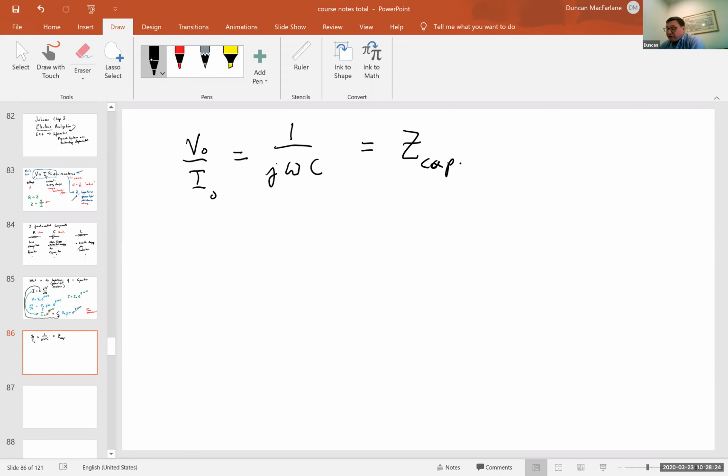So Rachel's 10 kilohertz component is going to have a different impedance than Matthew's 10 megahertz component. Matthew's 10 megahertz component is going to be 1,000 times lower in impedance or resistance, generalized resistance, than what Rachel has to suffer for the same capacitance.